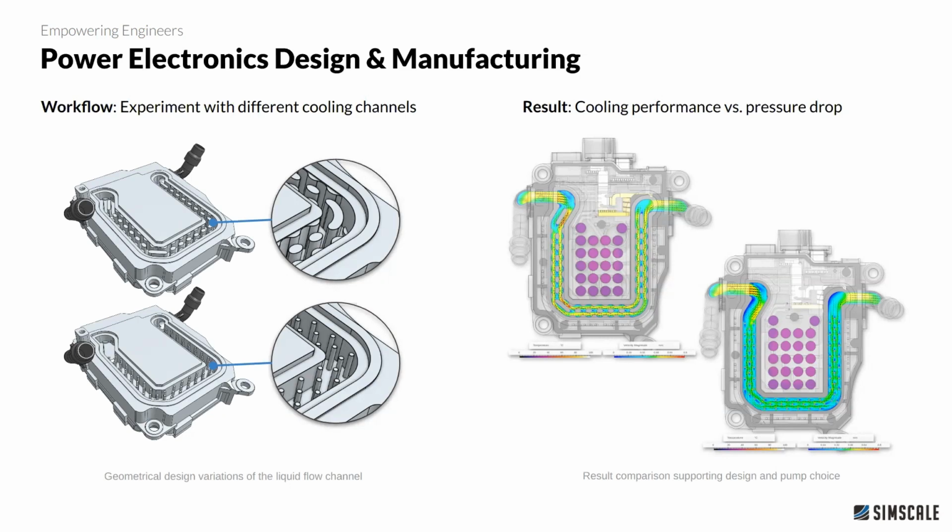In this case, you can see that probably this is going to be a trade-off of a pressure drop that you have in the liquid cooling channel and the cooling efficiency that in this case would be mostly targeted at the MOSFETs that get hotter from the switching losses when driving the essentially electric motor.